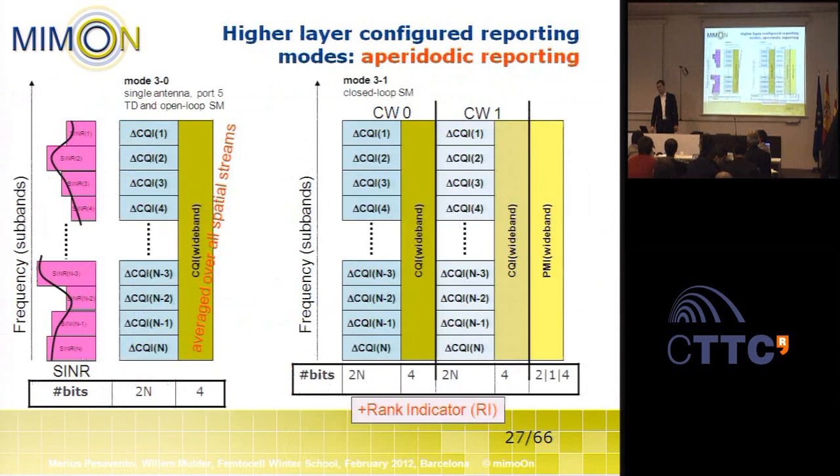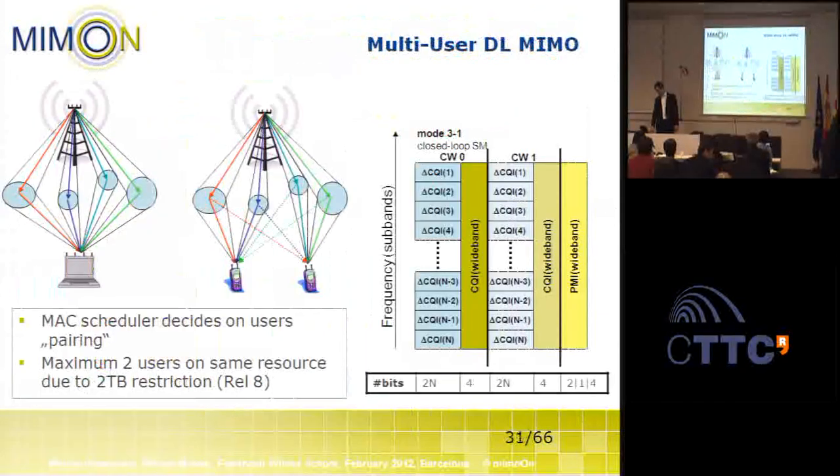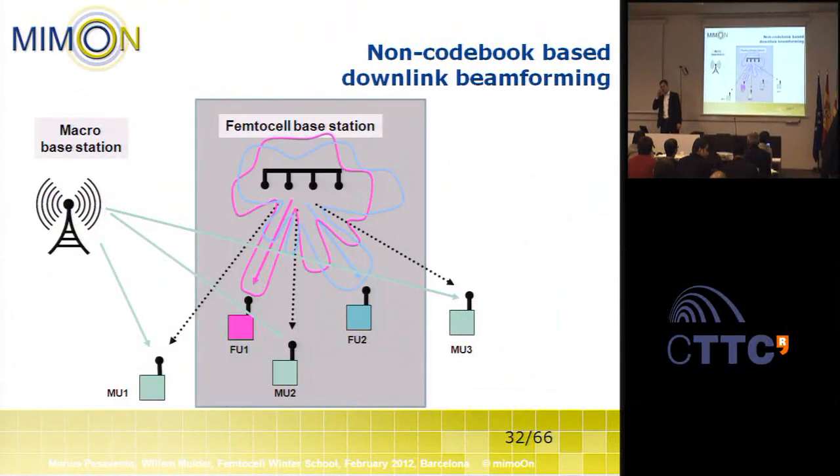So let's continue here. I was speaking about the femtocell, and that we need more degrees of freedom to design our beamformers freely, to form, for example, beam patterns as illustrated here, where we have deep nulls towards the direction of the mobile users connected to the mobile station, because of course an operator will only allow us to deploy a femtocell if it's not creating too much interference to the macrocell users.